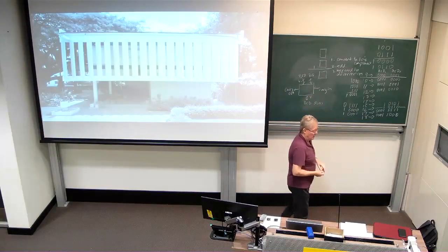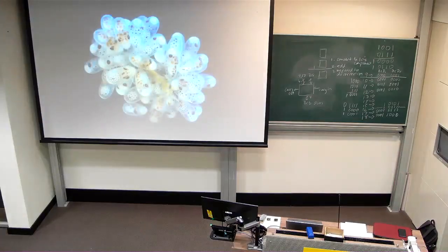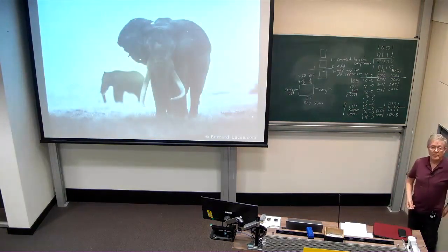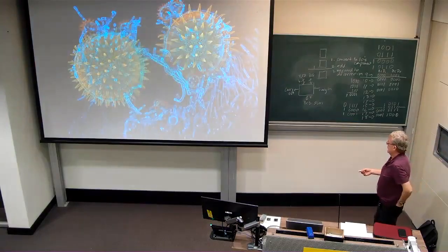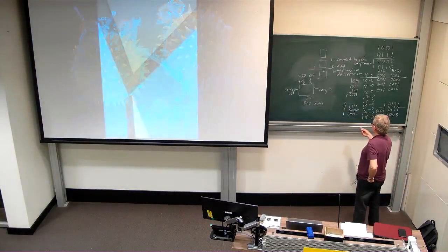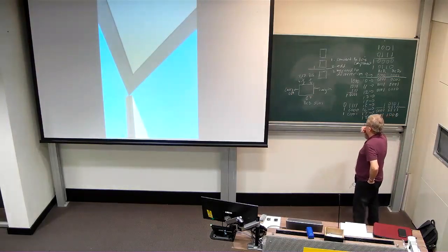How do we know we've got 10 or more as the result? Yeah. You can do the circuit where there's a 1 in the leftmost bit and there's a 1 in either the second or third position, then there is definitely 10 or more. Mm-hmm. Yep.